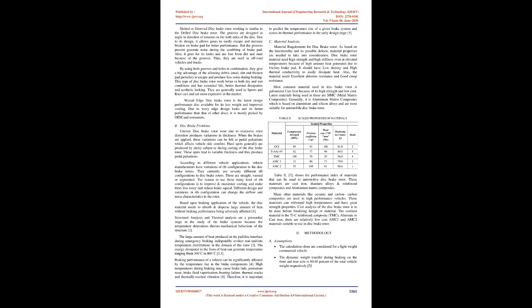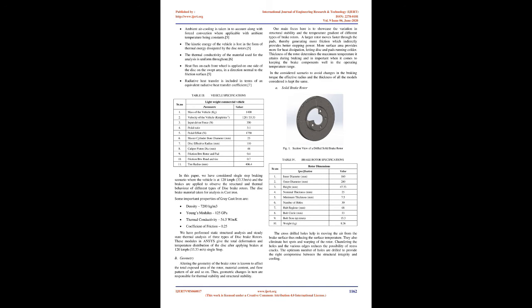B. Disc brake problems. Uneven disc brake rotor wear due to excessive rotor distortion produces variations in thickness. When the brakes are applied, these variations can be felt as pedal pulsations, which affects vehicle ride comfort. Hard spots generally are produced by sticky caliper or during casting of the disc brake rotor. These spots lead to variable thickness and thus produce pedal pulsations.